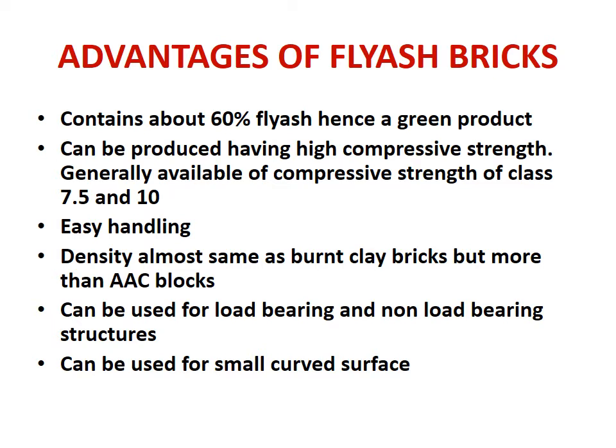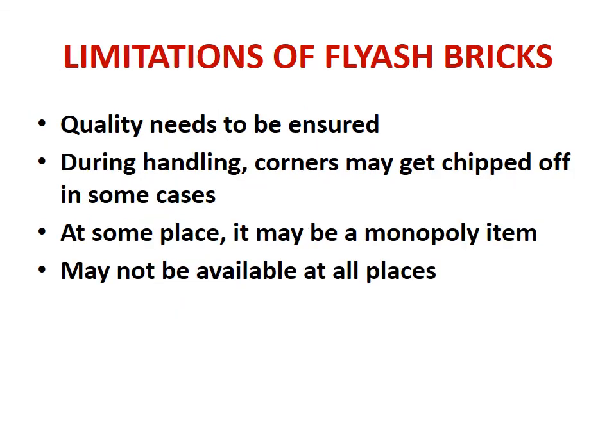Easy handling is there because of the size. Density is almost the same as burnt clay bricks, but more than AAC blocks. Can be used for load bearing as well as non-load bearing structures. This is a major advantage, as AAC blocks are not used for load bearing structures. And then they can also be used for small curved surfaces because of the size.